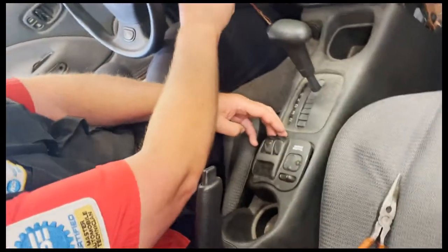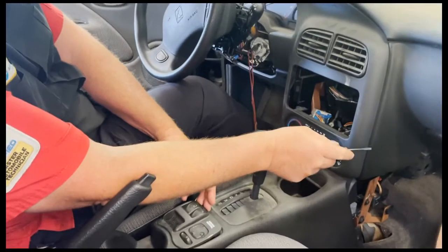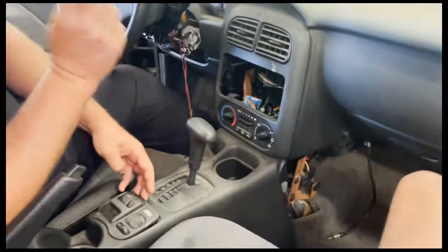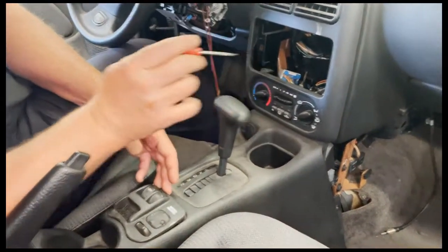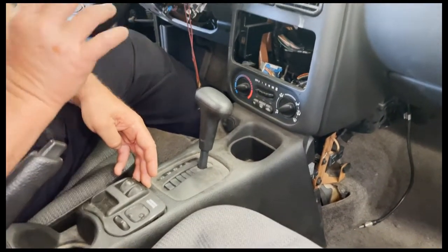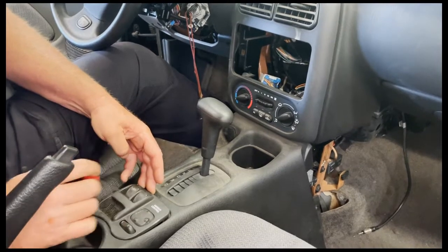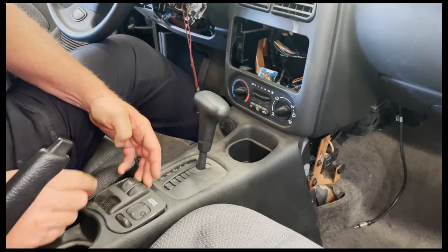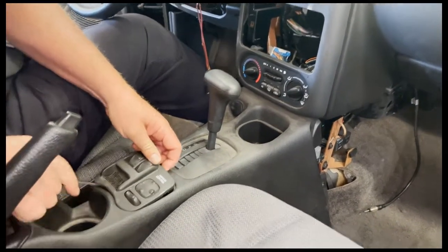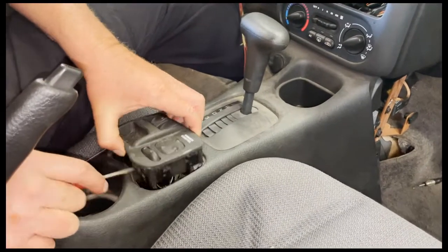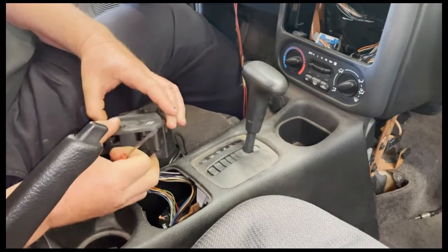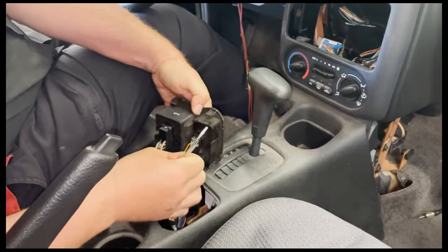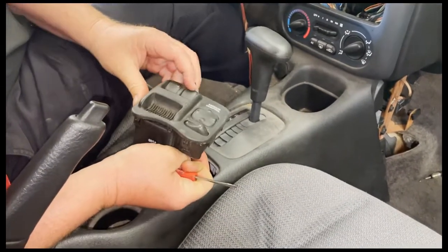All right, so we have our ignition key on, which powers up our relay. Based on the wiring schematic, the relay sends the power from the 30 amp window fuse to our switches. A good pocket screwdriver is what you need for something like this, because a lot of times these are just held on by little clips. So it's pretty simple. You have the window switches right here.